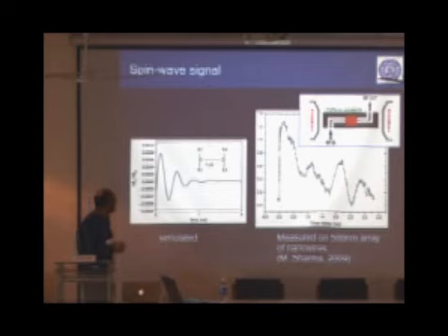And we've done some measurements on an array of nanowires in our coplanar waveguide, where the nanowires were connected at the bottom. So we are launching the spin wave in one end and then seeing the delay caused by the presence of the nanowires, which acts as a gating circuit.